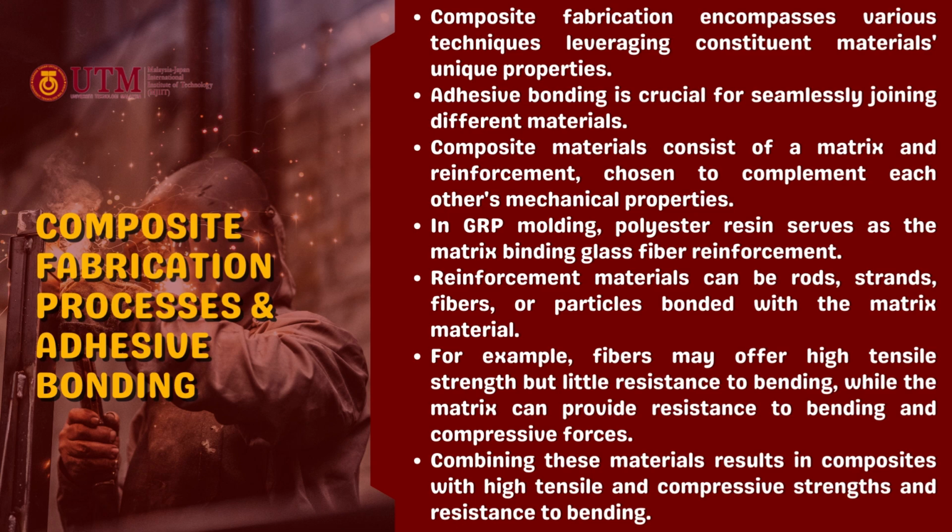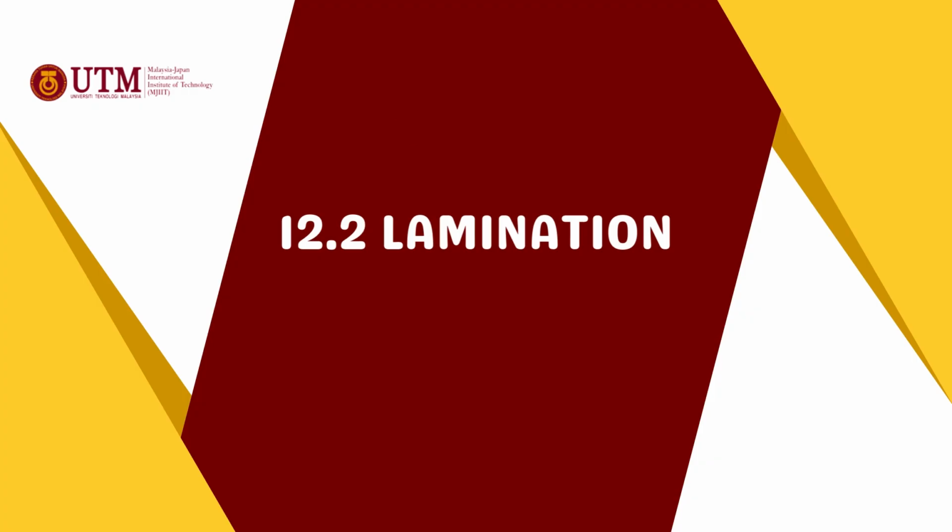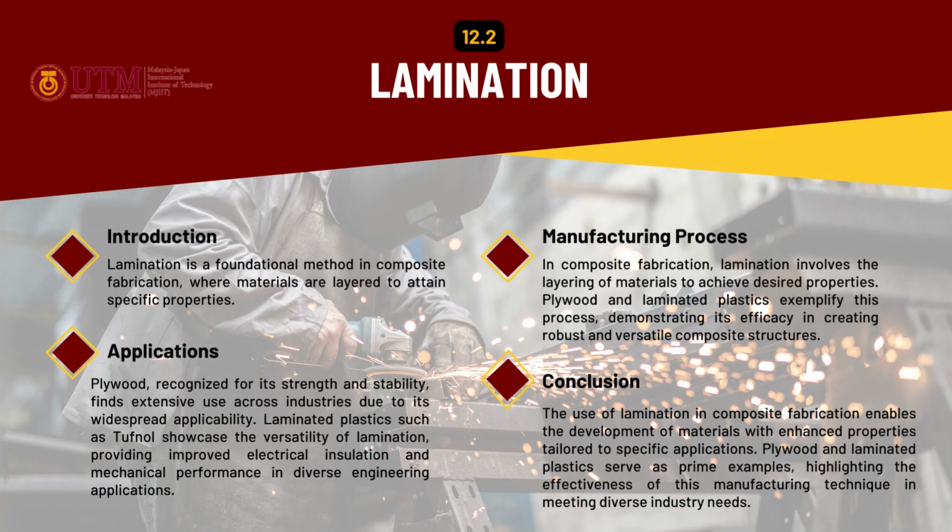Lamination. Lamination is a foundational method in composite fabrication where materials are layered to attain specific properties. Plywood, recognized for its strength and stability, finds extensive use across industries due to its widespread applicability. Laminated plastics such as Tufnol showcase the versatility of lamination, providing improved electrical insulation and mechanical performance in diverse engineering applications.